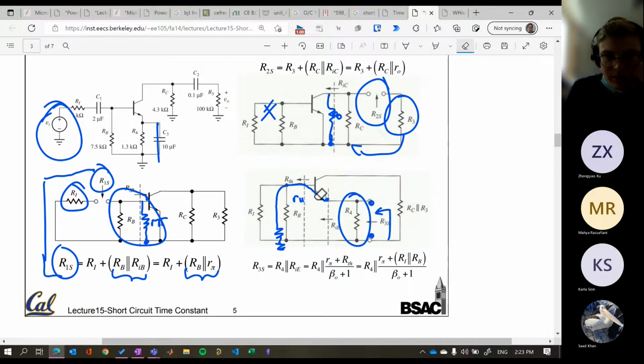I'll just neaten this up. So we've got this point goes to a resistor R pi, and then it hooks up in there. So let's combine these two, call it R Thevenin, RTH. And then let's add that to R pi. So we just have one resistor and then our BJT.